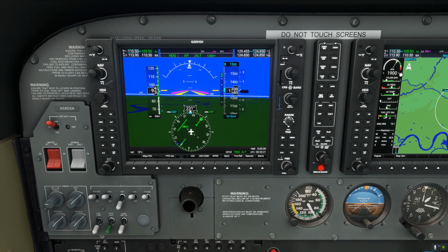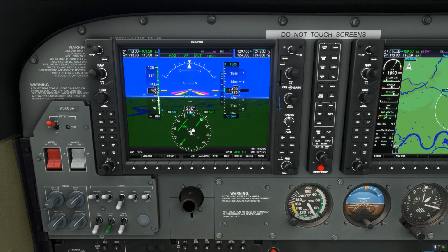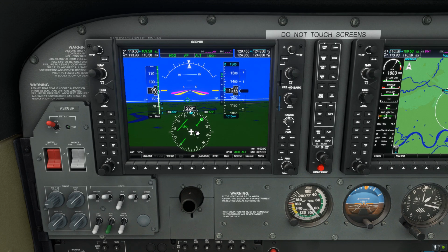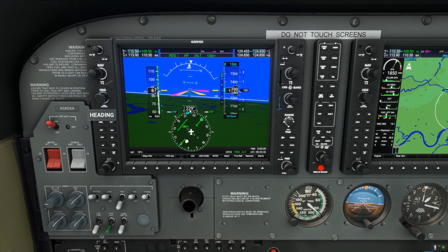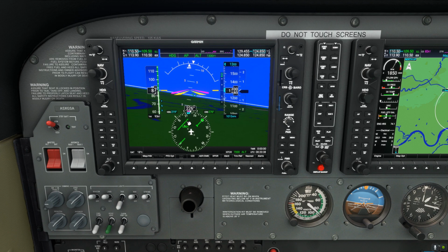There you go. I want about 1900 RPM here. That'll get us down to flaps 1 speed, or stage 1 flap speed, as you can see here. Just waiting for that line to move, and I'll move my heading bug. Let's do it up here. You can do it here, just to the left a little bit more, encouraging this course deviation indicator line to come inwards.